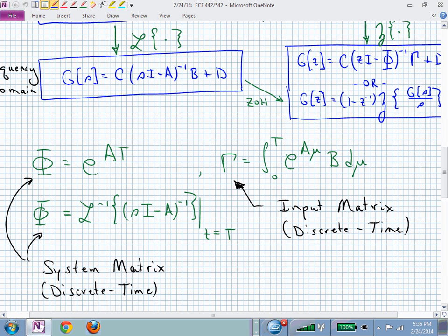That's going to be some matrix with S's all over the place. You could inverse Laplace transform each of those element entries in this 10 by 10 matrix. Oh, we said we could do 12 by 12. Whatever your A is, that's now this sI minus A inverse matrix. That will be a function of little t time, but if you replace that little t with capital T, you now have another way of thinking about e to the A capital T.